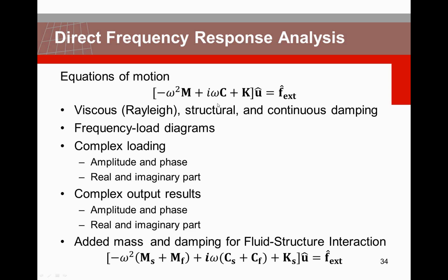While in the modal frequency response analysis, where you are limited to the modal damping, you only calculate your eigenfrequencies and your eigenmodes once, and then you can calculate the response from that, which is much faster than solving this complex equation of motion for each excitation frequency.